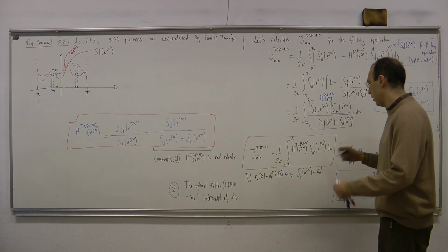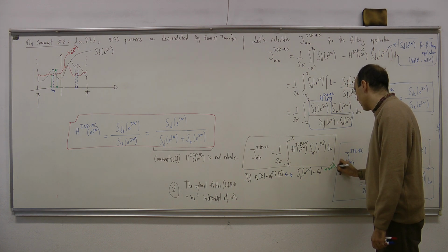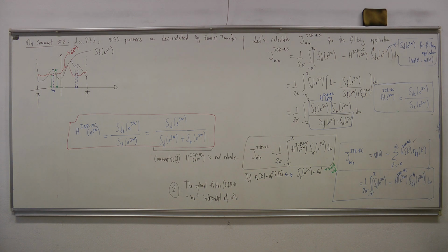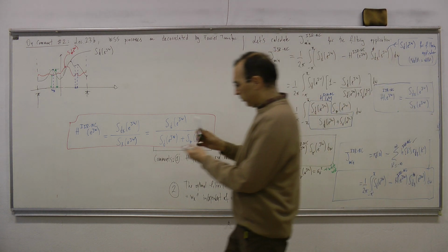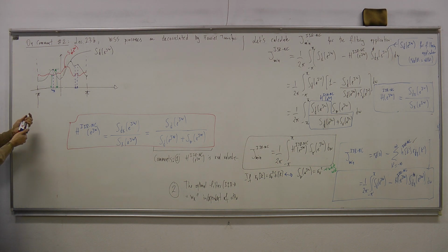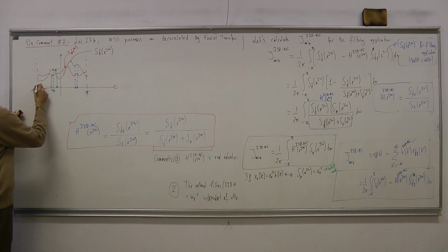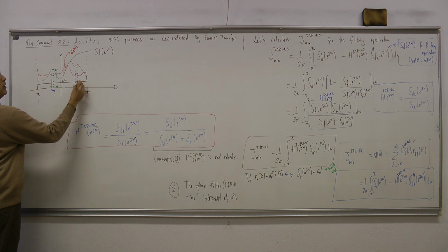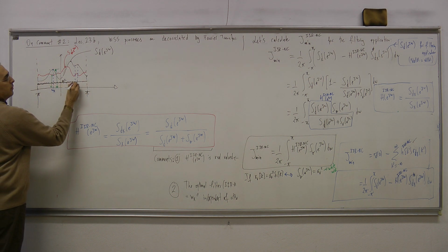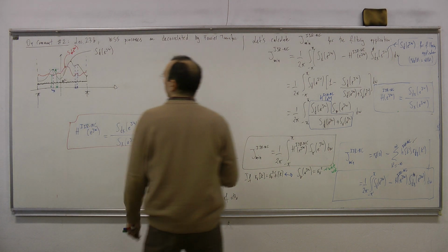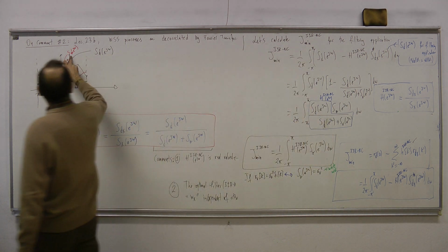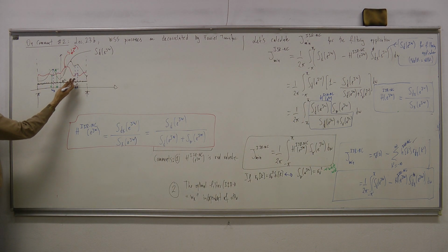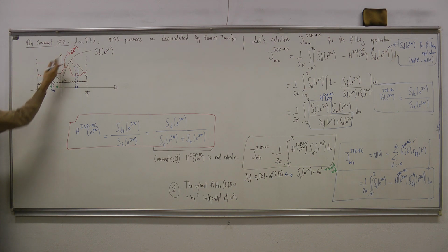Let me write white noise by this. As we have said, white noise means the following. In the spectrum, all of these frequency components, let's say it's flat, and I have, let's say, sigma v square. So they're equally weighted over here. All of the frequency components are present, but they're equally weighted. For example, this red one is clearly not white noise because some of the frequency components are more powerful in the generation of this noise process.